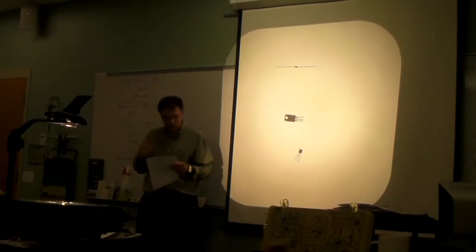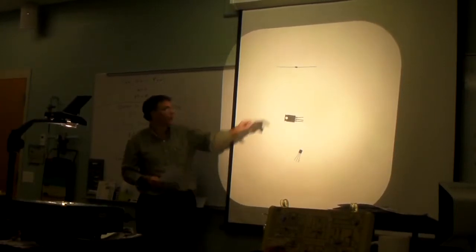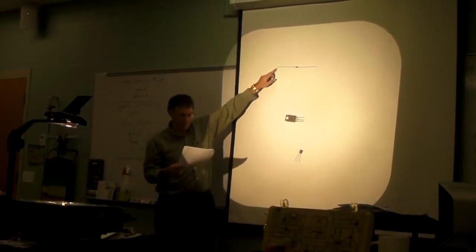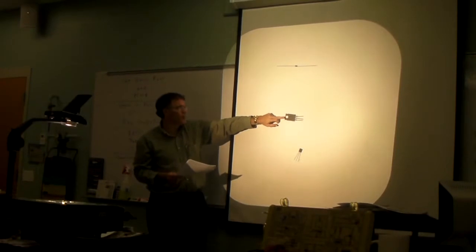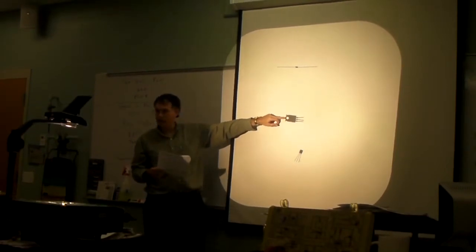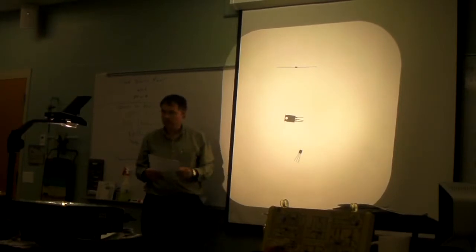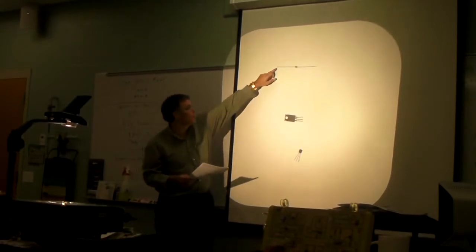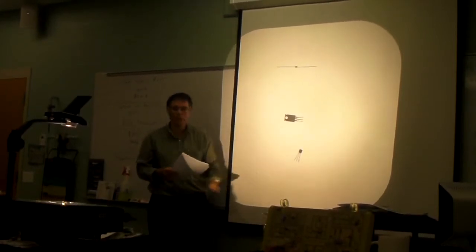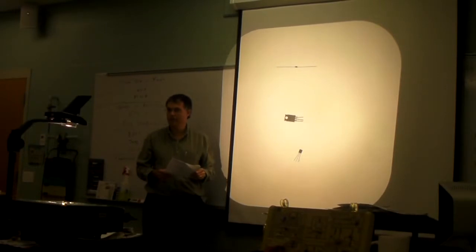The top figure uses the zener diode by itself, and the lowest figure uses the integrated circuit voltage regulator that we've talked about in the past. But if you look at the two center configurations, you'll see that those two voltage regulation circuits employ both a zener diode as well as a bipolar junction transistor.